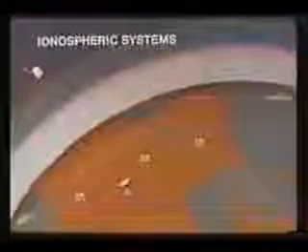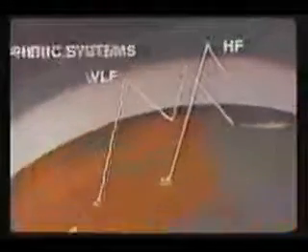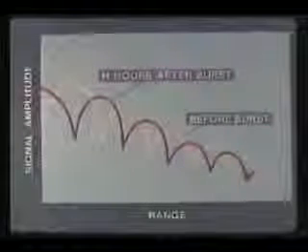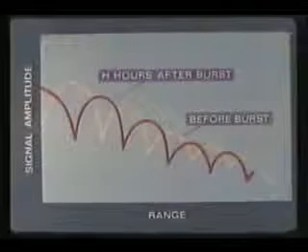A second general class of communication systems is dependent on the ionosphere. Changes in waveguide excitation factors and signal phase alterations may actually result in improved communications, but in an unpredictable fashion. Since the ionospheric D region is easily altered by delayed radiation from high-altitude debris, VLF circuits may be affected for many hours.